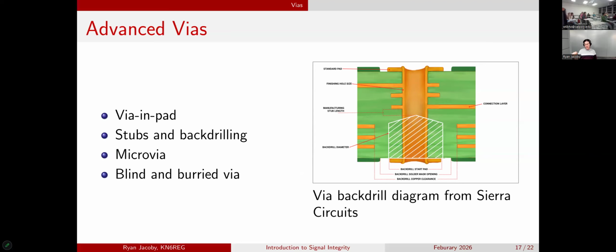So what's commonly done is epoxy gets applied to the board. Some non-conductive epoxy gets pressed through all the vias and actually plugs them. And then we'll plate over the top of them so that it is a flat pad with a non-conductive plug below, with the plated via around that. This provides a very nice way to put vias directly in pads. This is very, very useful for BGA packages, ball grid array, where for the landing pad of each of the balls on the bottom of the package, we can just place a via under it and pull the signal down into the board.